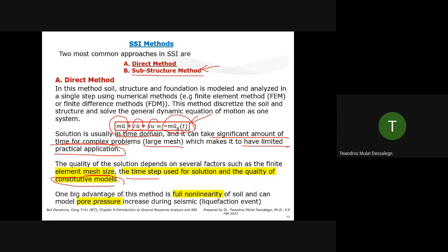One big advantage of this method is full nonlinearity of soil, and it can model pore water pressure during seismic liquefaction. This is the same method implemented in Plaxis and FLAC. Even if they are mainly used for geotechnical work, they do it in time domain.